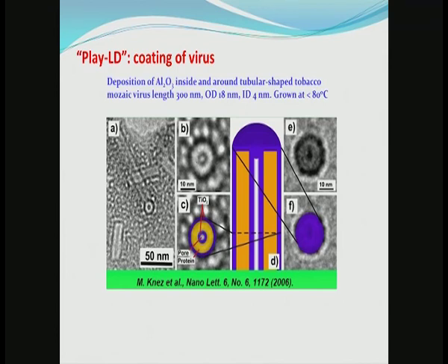What we have learned is that it is dependent on self terminating reactions, and sequential such self terminating reactions that are repeated in cycles so as to produce layers of great uniformity in thickness as well as layers that cover large substrates. Also, it is possible to produce multi-layer structures and laminates because of the great uniformity that atomic layer deposition provides.